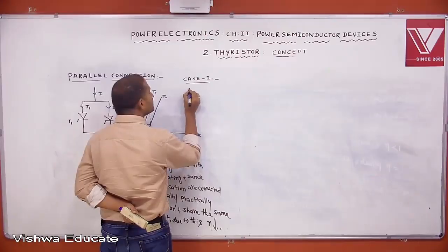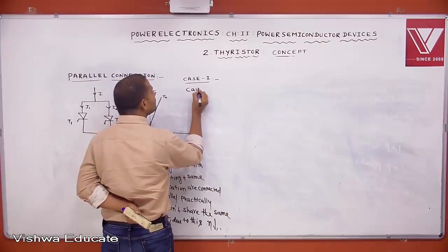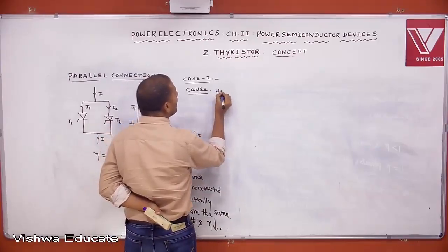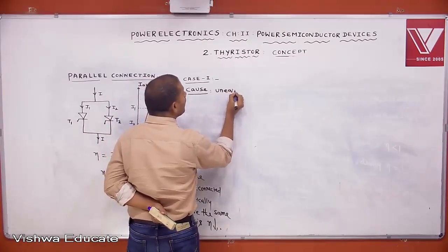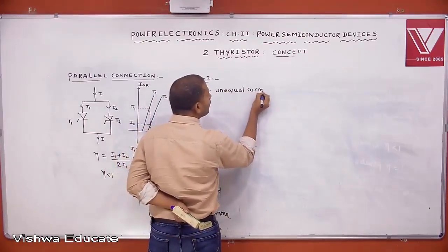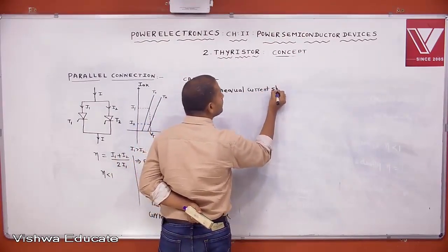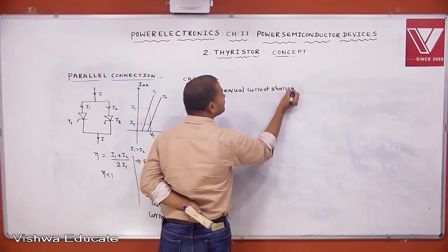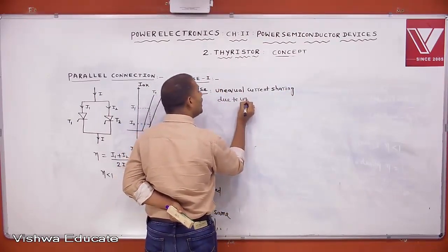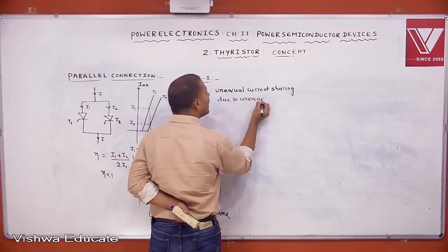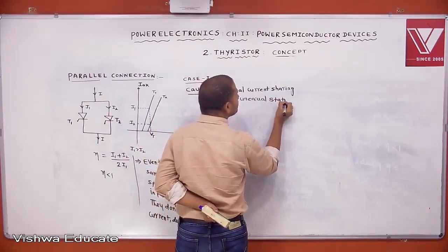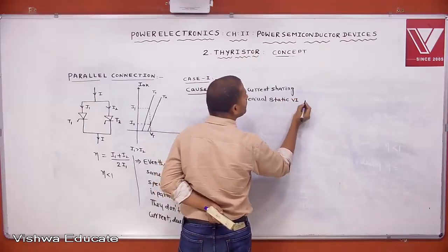What is the cause? Unequal current sharing due to unequal static VI characteristics.